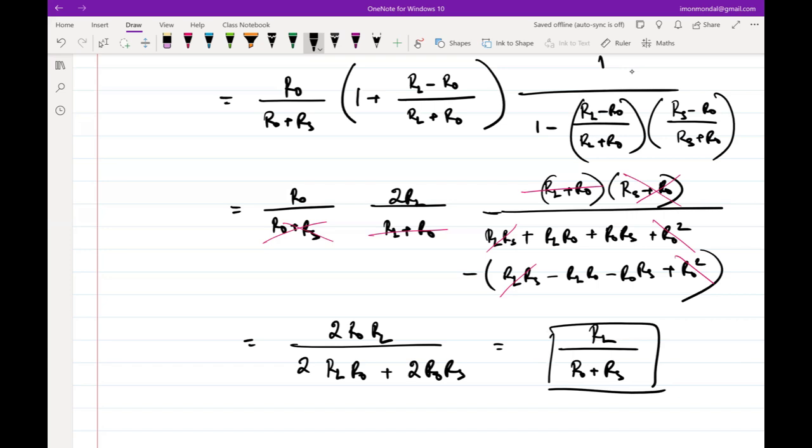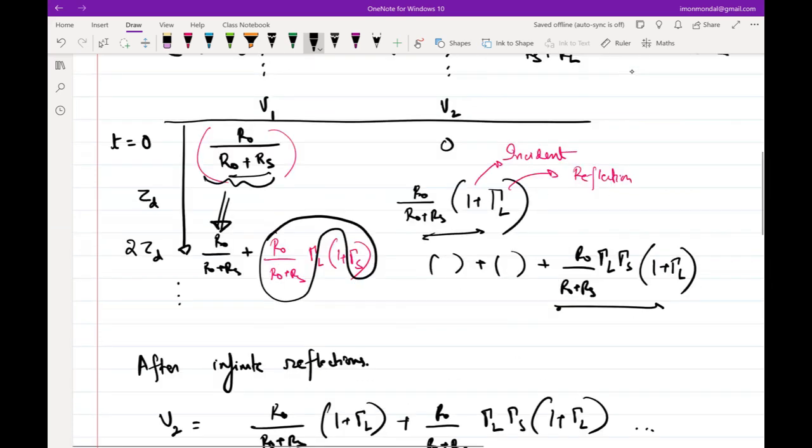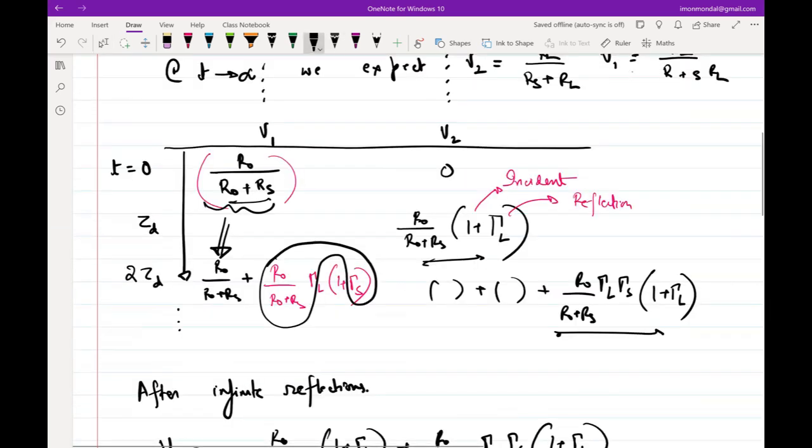Right? So you see, after this very simple thing that we normally do with a resistor divider, you can come to the same conclusion at steady state when you use transmission lines also. And this is a much more generic way of dealing with circuits, because truly in each circuit you are going to have delays. There is no getting away from it. Just the lumped element approximation helps us to say that the delay is 0, right? So if the delay is 0, what intuitively, visually, is going to happen? So visually, at V2, right?